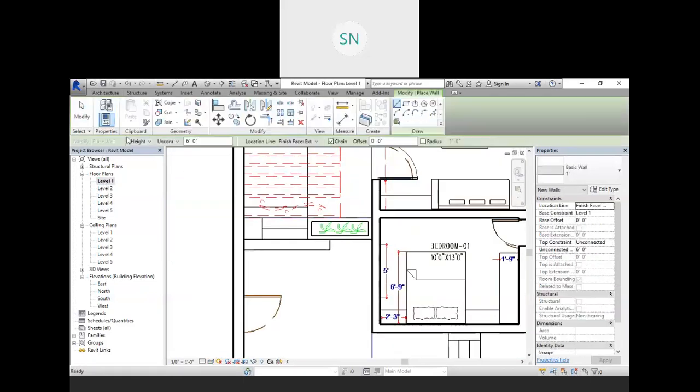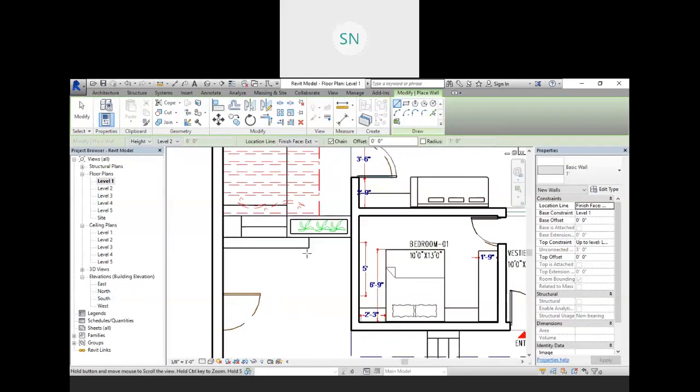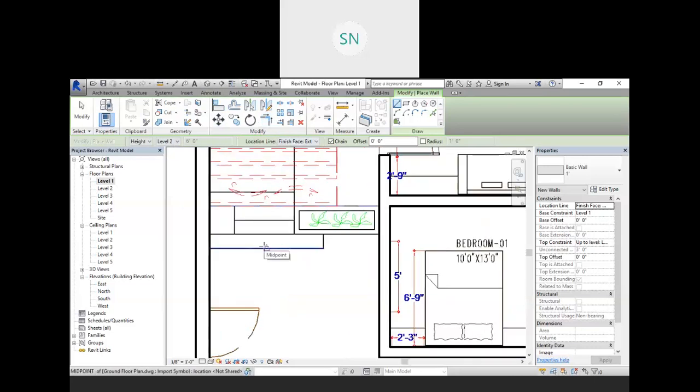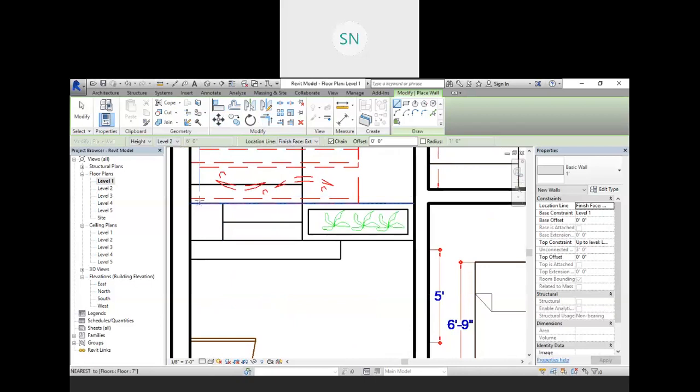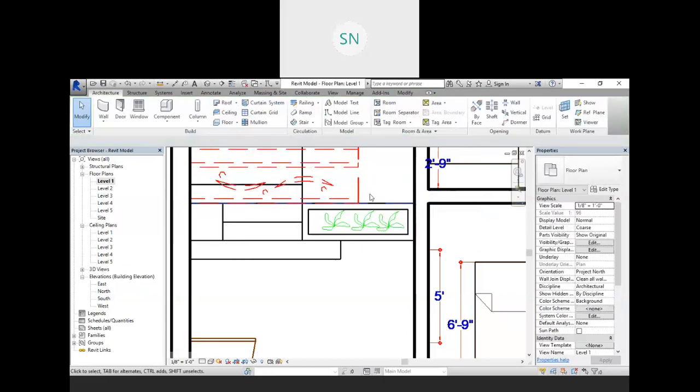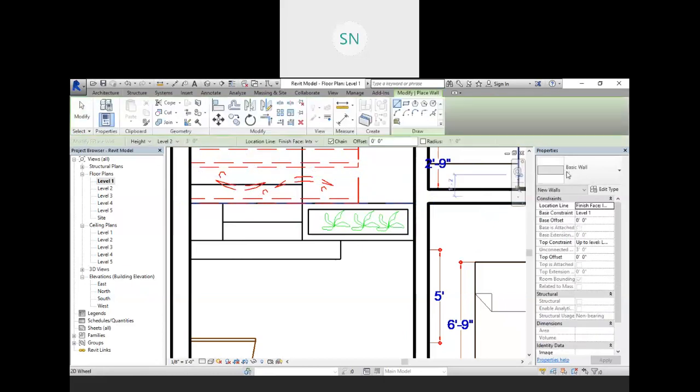Click on the wall from level 1 to level 2, and it should be inside, so make sure my justification is exterior side. Okay, and from here, actually let's take interior. Why is this a 1-inch wall? We want a 9-inch wall. 9 inch.